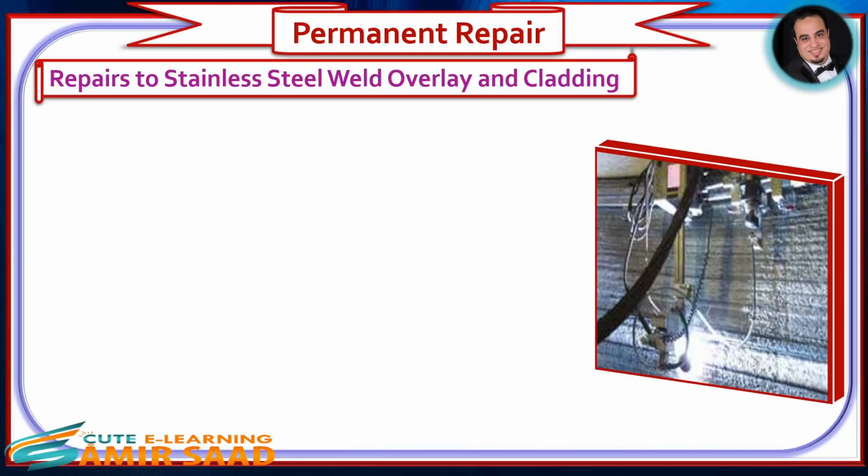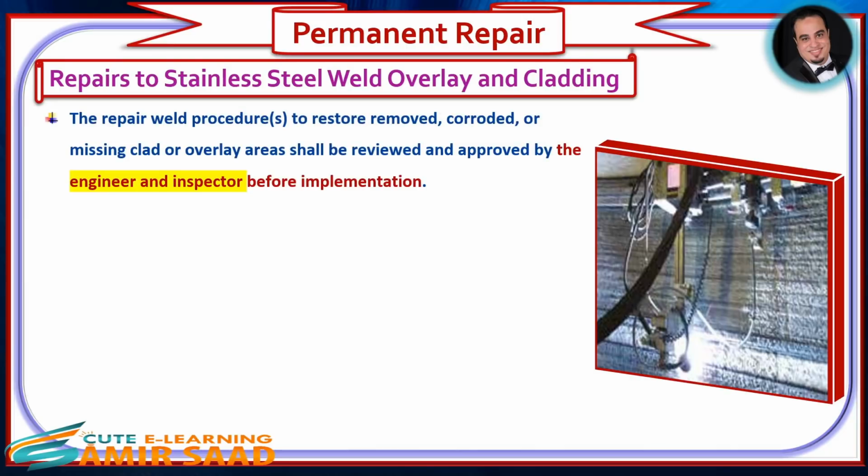Repairs to stainless steel weld overlay and cladding. The repair weld procedures to restore removed, corroded, or missing clad or overlay areas shall be reviewed and approved by the engineer and inspector before implementation.